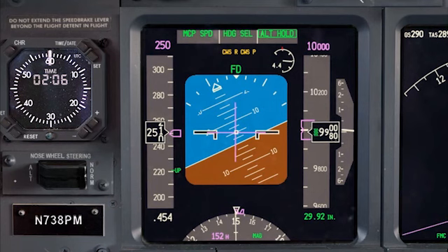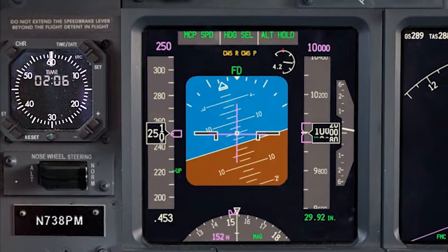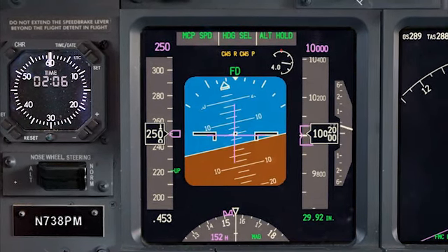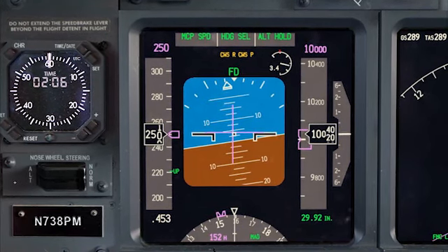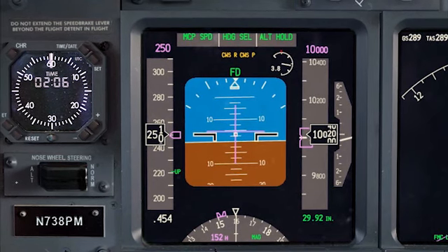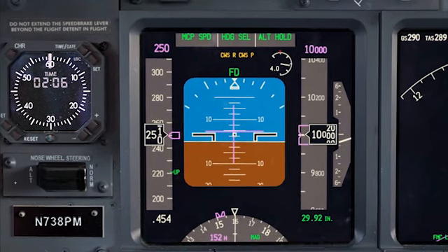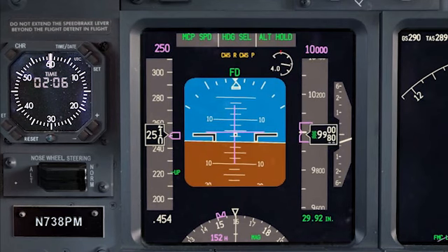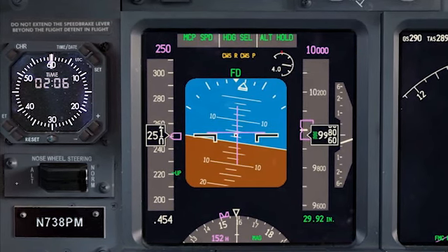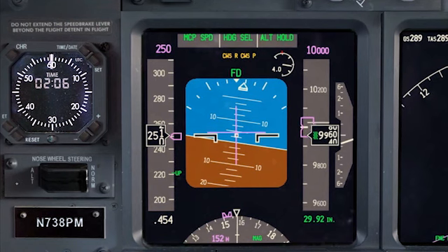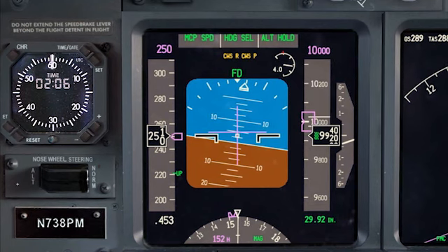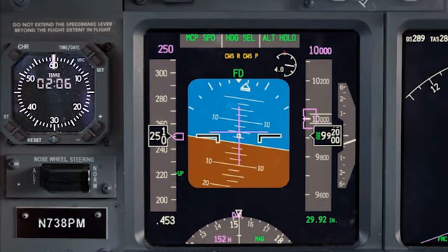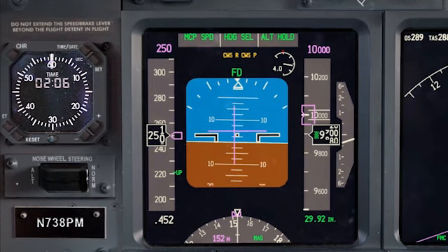In an actual example, although the MCP is set in heading select and level change, the pilot can only set where he thinks the aircraft should go to hold that setting. If a variable changes, say airspeed, wind direction, and so on, the FCCs will undoubtedly make some minor adjustments to what it thinks should be done. The autopilot would jump on those commands and make the adjustments, or it would be reflected through the flight directors. Control wheel steering, however, remains in the same commanded position. Sit, stay.